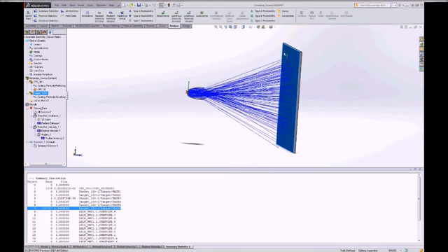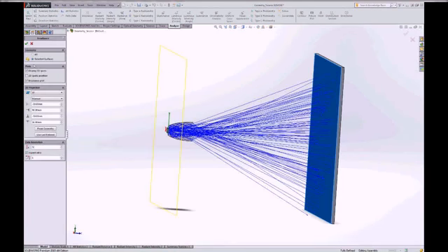So by highlighting this surface, when I come up and choose to do another calculation, it will only be looking at the energy associated with any surface or surfaces that I have highlighted. So let me click on irradiance here. And you'll notice it does tell you that it's going to be on the selected surfaces. Don't worry, if you didn't do it in advance, you could do it at this point in time.